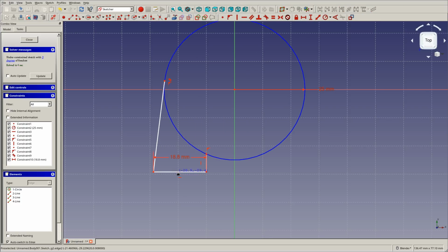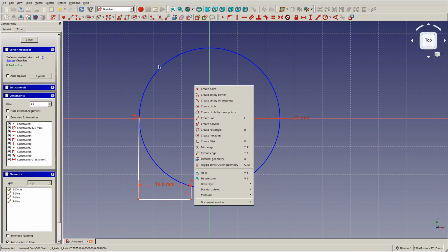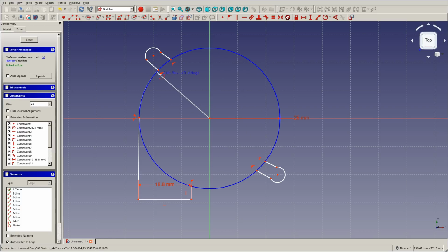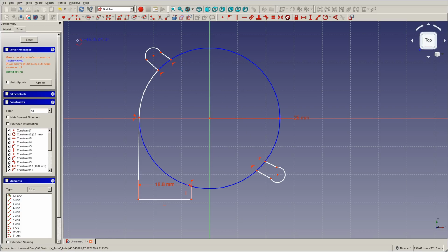There we go. Can just move it a little bit. And there's the two little screw holes, which we have to do as well. So I'll just make little arcs like that, and semicircles that connect them. Okay, so now we can do the final arcs that connect everything. And this is going to over-constrain it a bit. It's all right, we can always delete some constraints later.